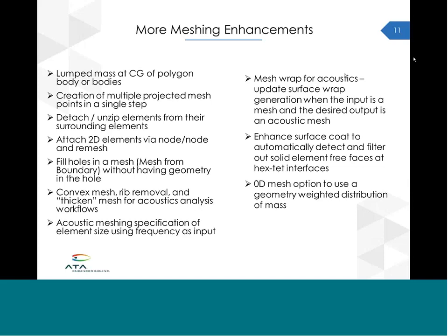as an input. And the reason for that, for those of you who aren't intimately familiar with acoustic analysis, is that if you want to have high fidelity results, it's important to make sure that your element size is such that you can capture the resolution of the frequencies that you're interested in. There's a mesh wrap for acoustics, which is similar to this idea of creating a convex mesh around a body.